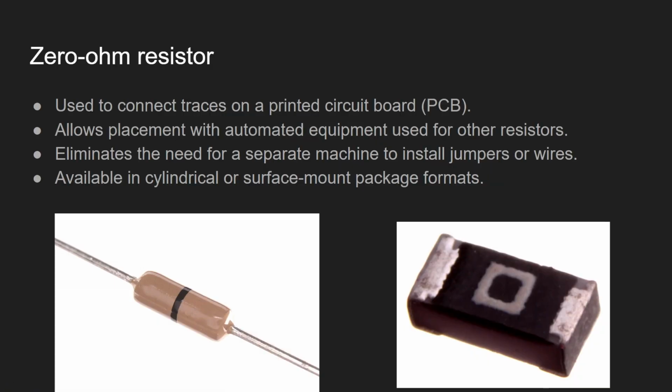And in real life, you may also see a 0 ohm resistor, which, no, you're not going to be asked to read in the exam. This is just to help you manage your PCB board. They have a very negligible resistance and act like a jump wire, so that you can make your PCB cleaner. Sometimes the place may be hard to connect, and it is very ugly to use a jump wire, so they just put a 0 ohm resistor over here.